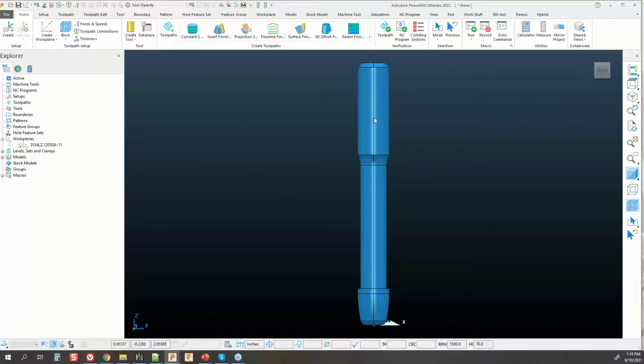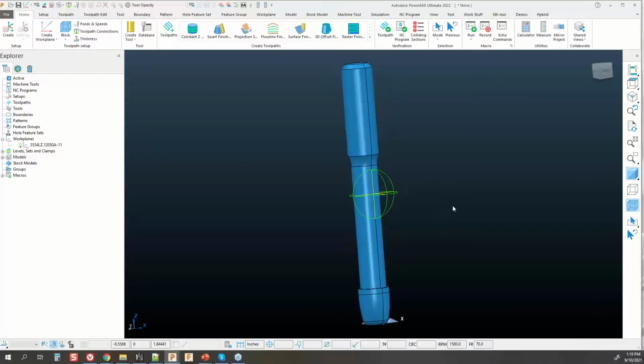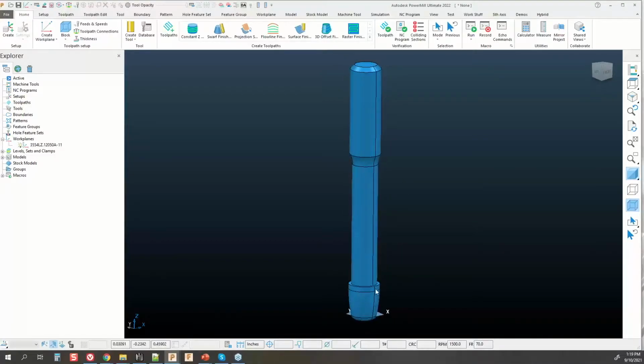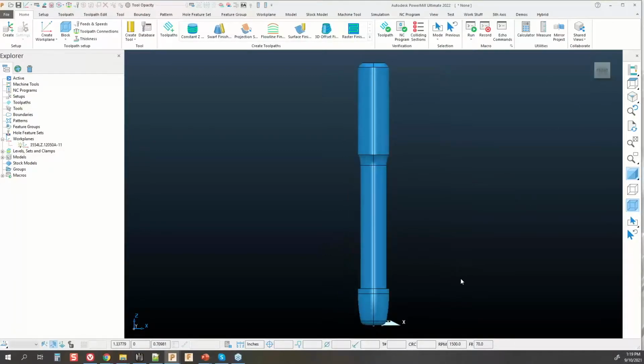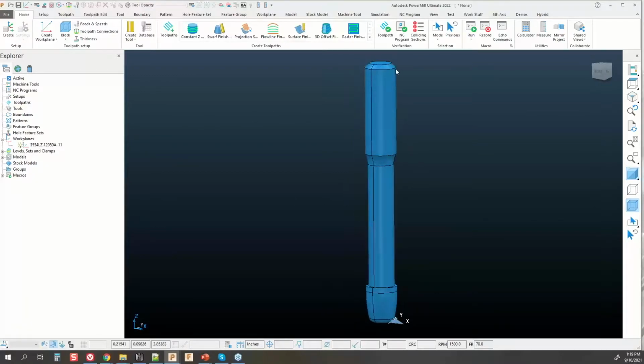And what I want to do is get the segment of that tool. Now, there's two schools of thought here. One is that you have that side profile along that tool. My experience is that occasionally these segments of these profiles can be broken up and can cause problems. So when I look at my front view in PowerMill from my zero origin position, I want to have a full surface there to split this by, utilizing some of the tools that PowerMill needs to extract that